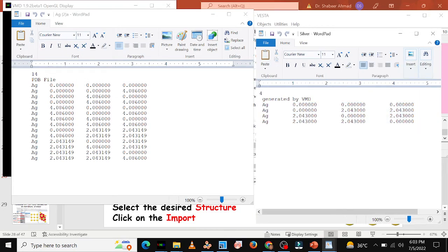Okay, so now I will take these coordinates and write them in the SIESTA format. In the next video, I will show you how to write the SIESTA input file, because this file is in free data format style, so you can write it in WordPad or Notepad or even in MS Word. It does not matter, but the extension should be filename.fdf.